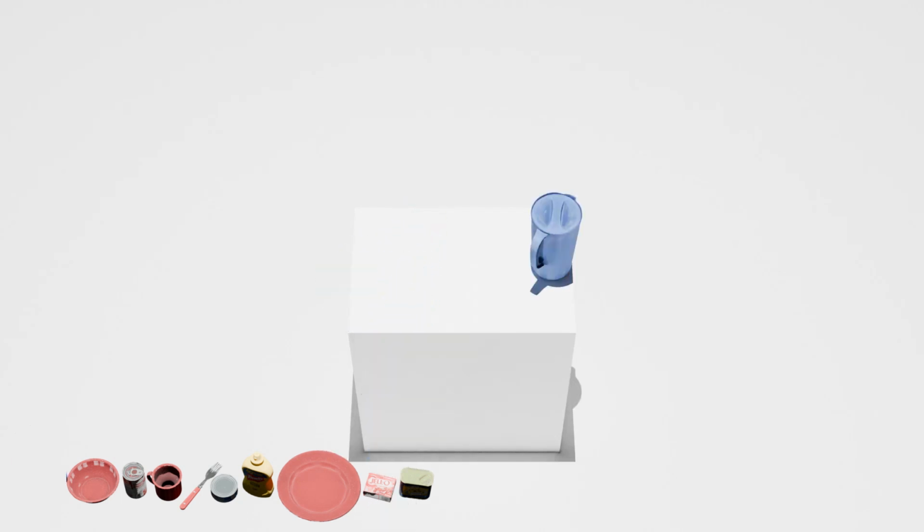If the object is not stable, such as bumping or dropping, its movement trajectory will be recorded and used for the next attempt until it gets stably placed. After that, the next object is ready to place. The queried region and the points cloud observation will be updated for the new placement. This iteration is repeated until all objects have been placed stably.